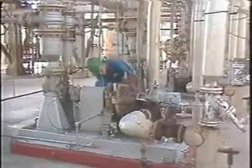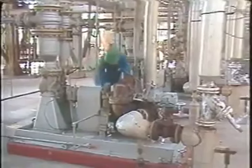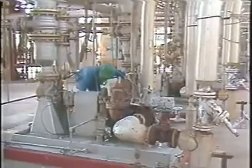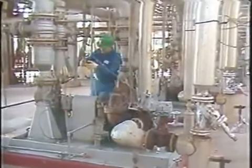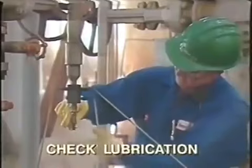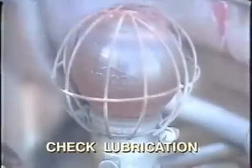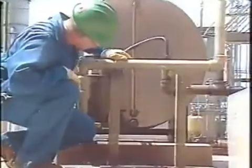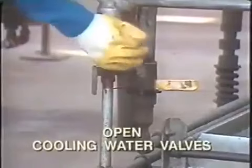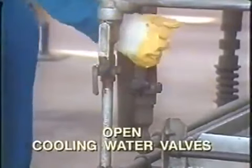In addition, pumps should always be operated in accordance with standard operating procedures for starting and stopping the pump. Failure to observe standard operating procedures will result in serious damage. Before you start the pump, you should always check to see that lubrication is available to all bearings. In oil-lubricated bearings, check the oil level in the bearing housing reservoir and add the proper type of oil if necessary. For pressure or mist systems, check the level in the reservoir and be sure the mist generator system is operating. If the pump is cooled by water, open the inlet and outlet valves to allow the cooling water to circulate.